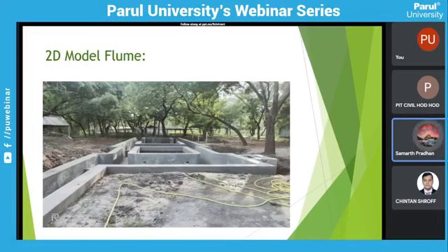The standing wave flume is for discharge measuring. After water passes through the standing wave flume, another chamber is also there. Before entering the model, the water should be very still, otherwise you cannot attain the natural condition. So again one chamber, a downstream stilling chamber, we are constructing.